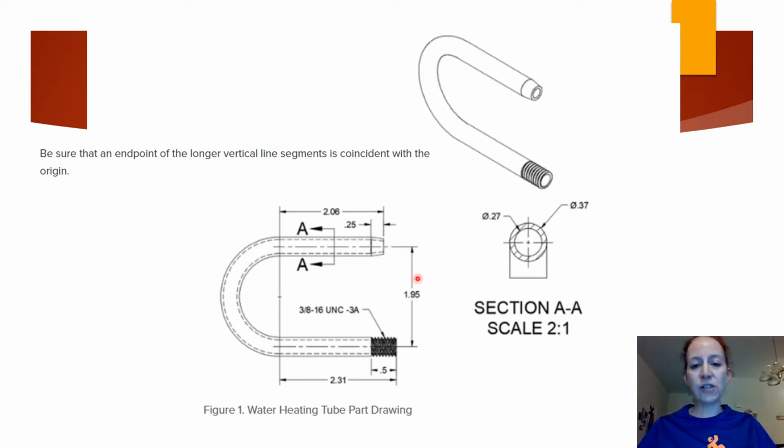There's one dimension that's missing on it though, and I'll talk through the process for how we'll design this. So we're going to start by drawing a horseshoe shaped figure in the XY plane. You want your origin to be down at this end. So you're going to start at the origin and then draw some kind of horseshoe shape like this, not including the tapered end. The tapered end was causing some issues. So on the XY plane, it would look like this.